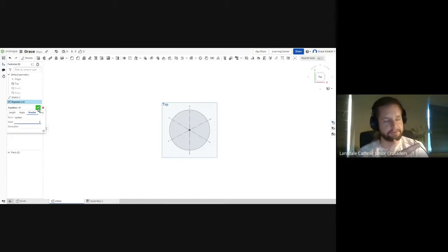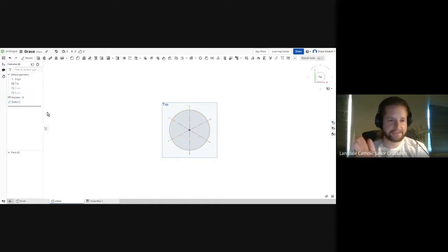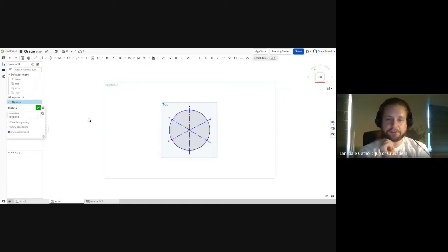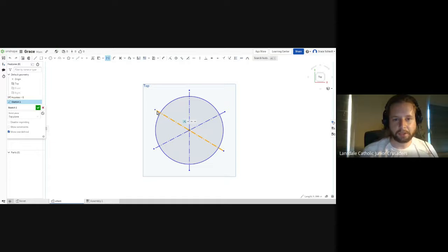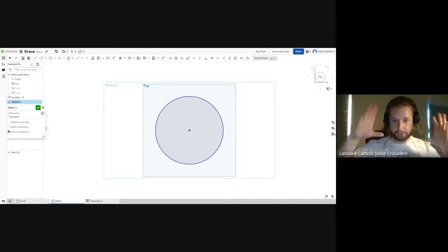The one that was in the drawing, or the one that you had, has like 6, it looks like, right? Yeah. Cool. So let's do 6. Good. You ordered it before the sketch. Fantastic. All right. Now in your first sketch, I want you to just make the ring where you want the spokes attached to. We won't make the spokes just yet, so you can actually remove all those if you'd like. And if you want to make it a solid core one, just dimension that solid core so that it's constrained.